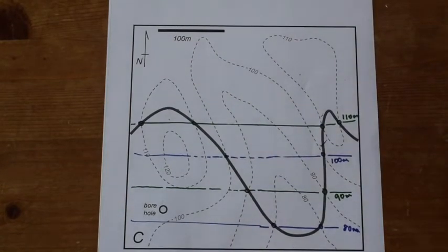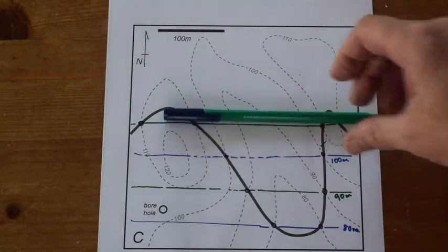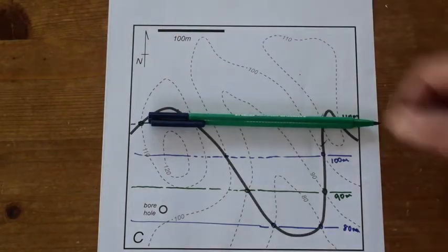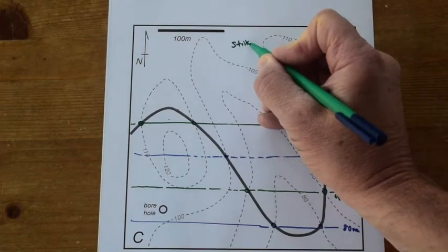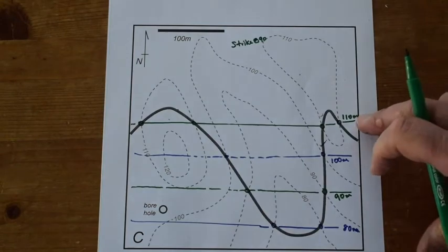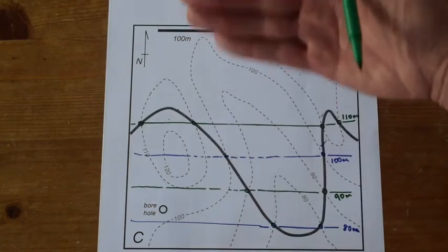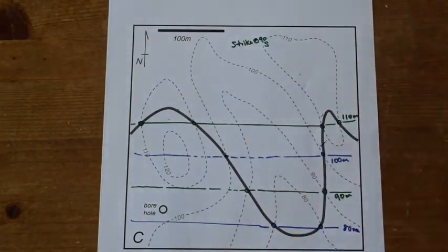Finally, we can estimate the orientation of this boundary with a strike and a dip. Well, the strike is the trend of the structure contours. They're otherwise known as strike lines. And you can see from the relationship to the north arrow that the strike is 090. And the dip direction goes from 110 to 80 southwards, shallow level going deeper this way, so therefore it's dipping south. To find out what the dip is, we have to use some trigonometry.